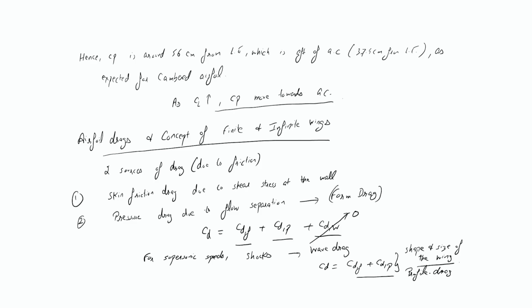So I have taken the names form drag, profile drag, and wave drag. We are ignoring wave drag as of now since we are discussing subsonic aircraft. So CD equals CDF plus CDP, and let us go ahead with this assumption.